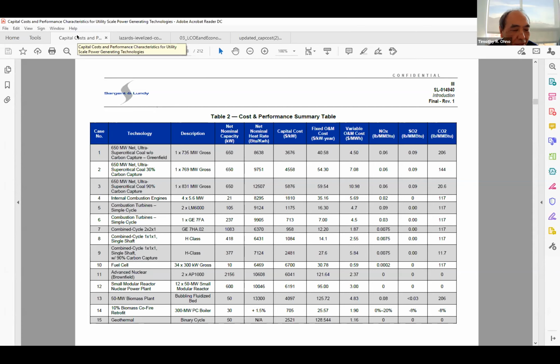So now what I've got is an upfront cost of about $6,000 times 600 kilowatts. So that's 3.6 mil. So I put in 3.6 mil initial for my investment. Then I've got another big chunk, which is my fixed O&M cost each year. So that's half of my C1. But now I have to take the variable O&M cost also. How do I add that in? And Kylie was almost right. So her suggestion was to take the variable O&M and multiply it by the nominal capacity.